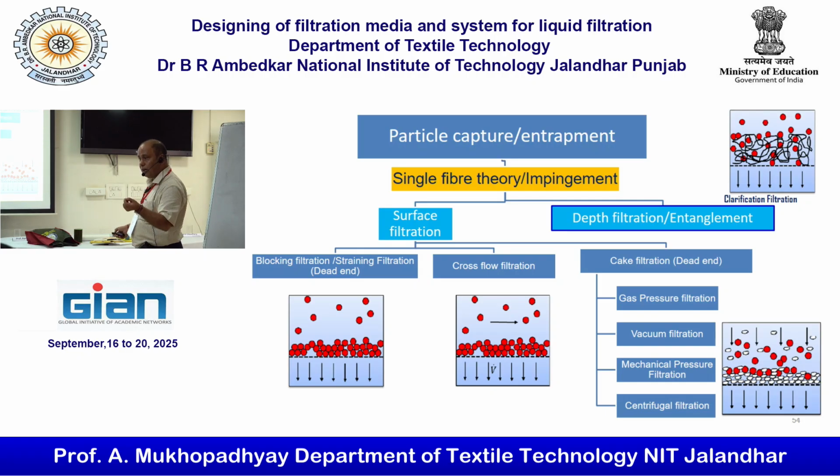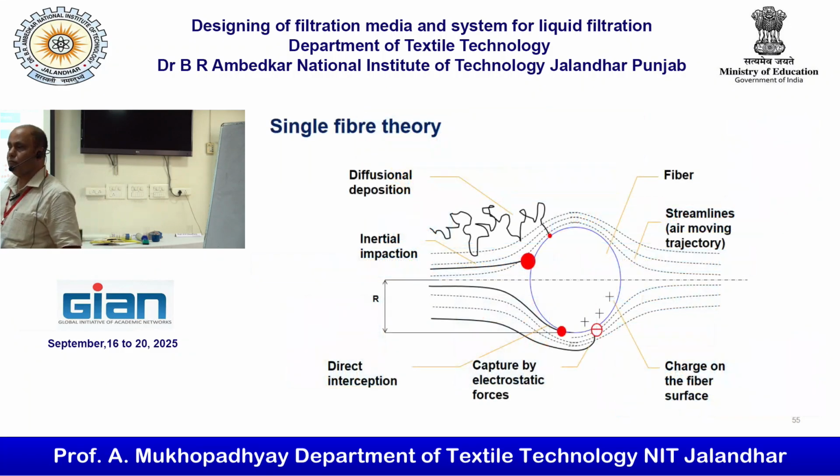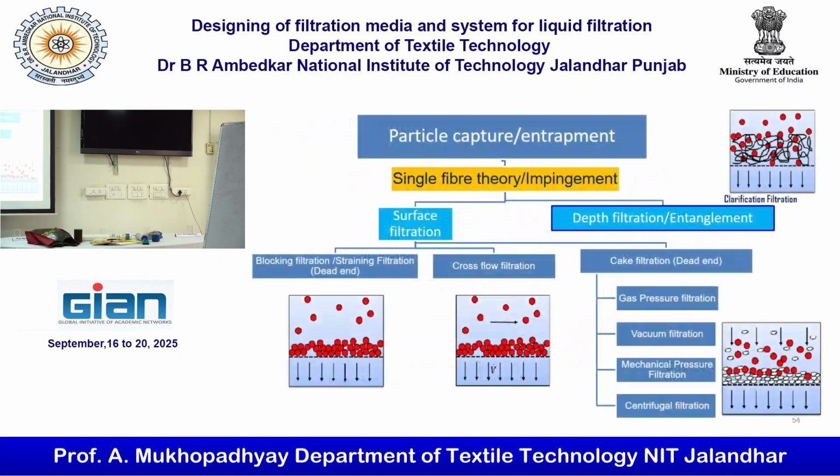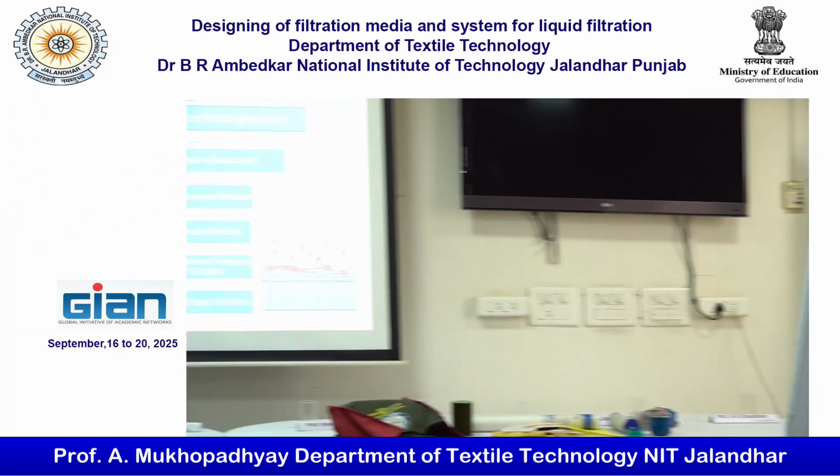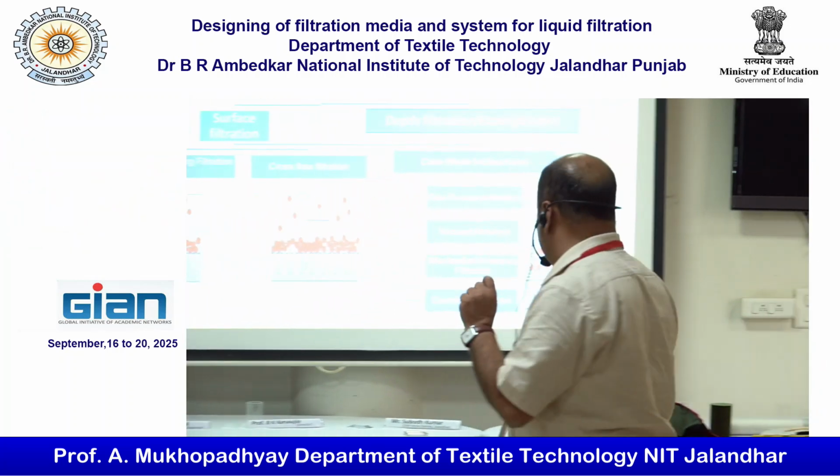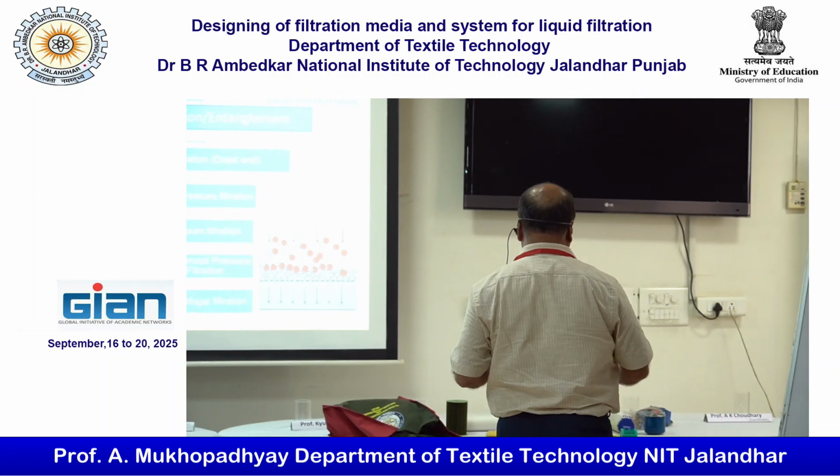But if the sludge content is low, in that case we can go for vacuum filtration and gas pressure filtration. So I think, yes, depth filtration means particles have to be arrested up to a certain depth.